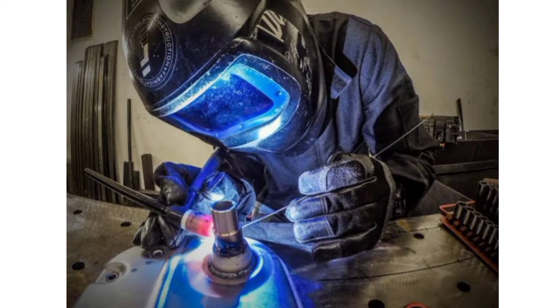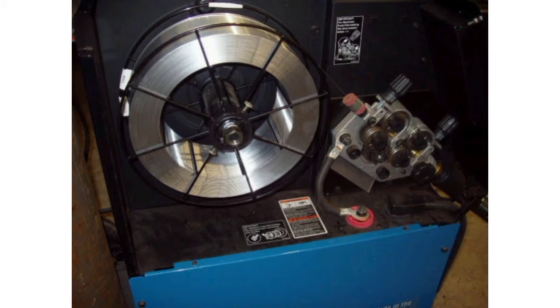Difficulty of process is the second point of difference. As with TIG, you have to hold the welding torch in one hand and the filler material in the other hand, which makes it difficult for inexperienced users. MIG's method of continuously feeding wire makes it an easier technique to handle than TIG.